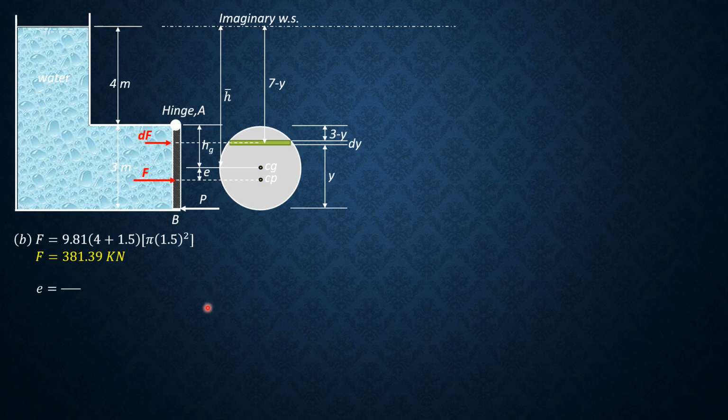Next for E, E is I sub CG over area times barred H. So I sub CG of a circle is pi over 4 times r to the fourth, divided by area pi r squared, then barred H is barred H. So simplifying, that's r squared over 4 barred H. Substitute the value of r, which is 1.5 for the circle, 1.5 squared over 4 times 5.5. So E is equal to 0.1023 meters.